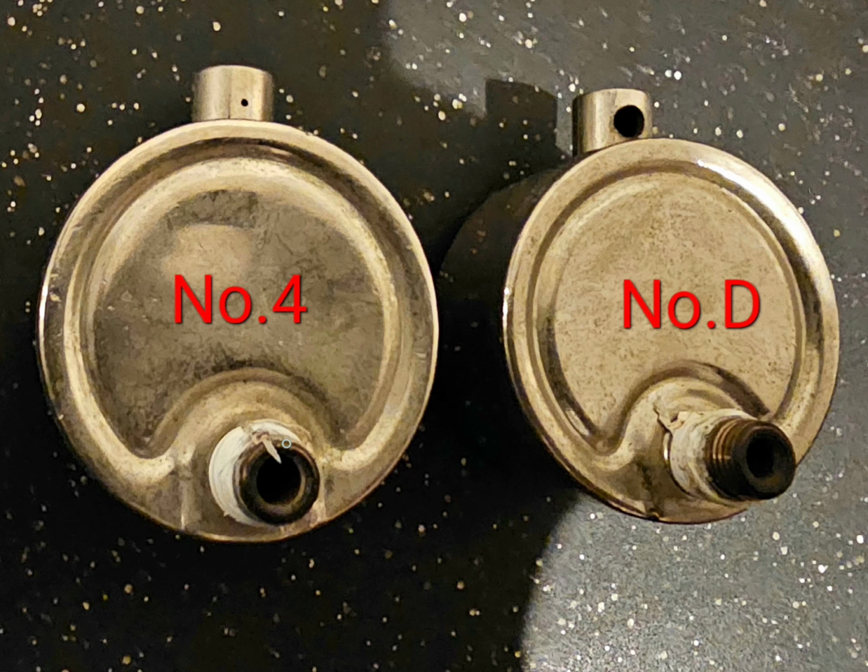Now with the number 4, this is the same thing that you've seen in the Hoffman. You've got the inlet capacity, but you don't have the proper outlet capacity. So when it comes down to what he's describing about radiators having a drop away pressure, if you're slapping this particular air vent on a cast iron radiator, you might have that problem.